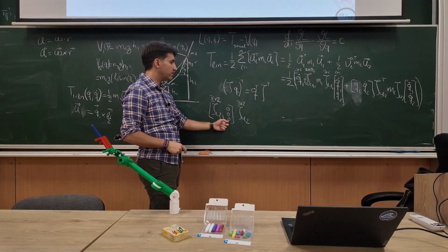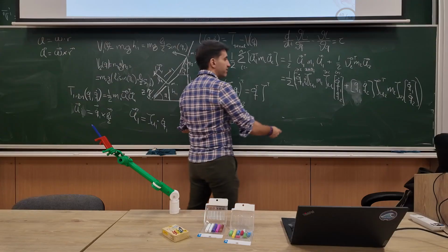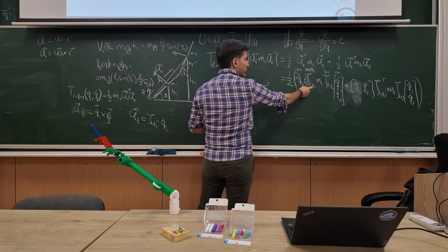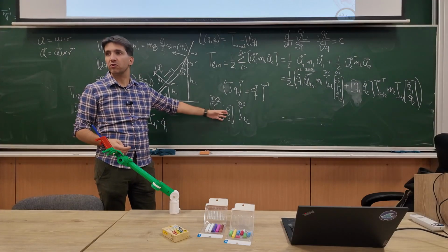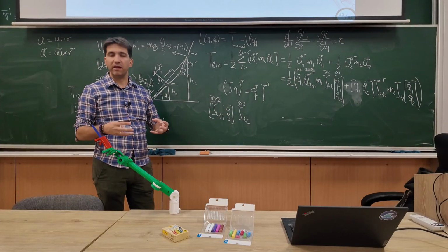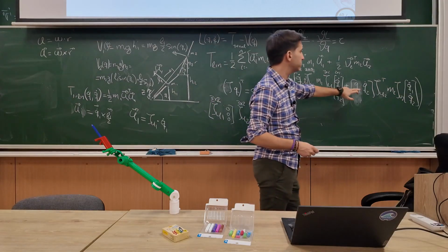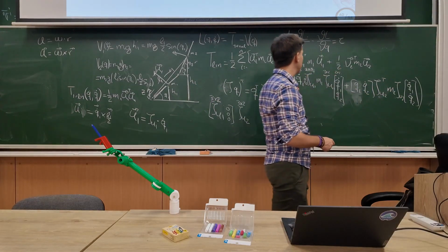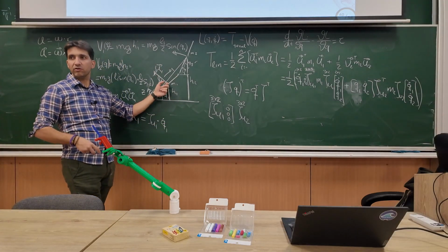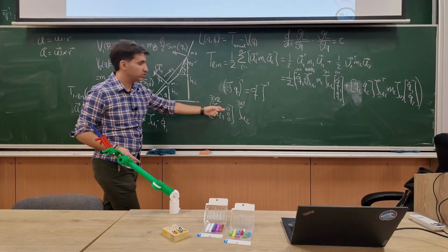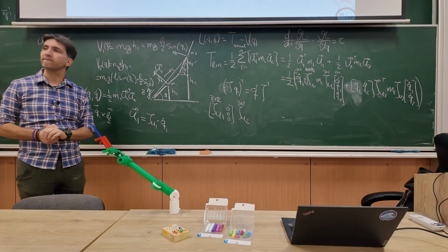Since I put 0 here, everything that gets multiplied with Q dot on this Jacobian will have 0 effect. So I can keep the same dimensions for these Jacobians and these Q's, and I still don't add any effect for Q2 here because the effect will be 0. We add zeros just to ensure equal dimensions.